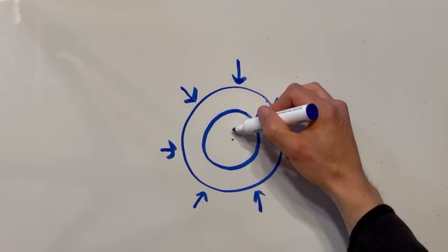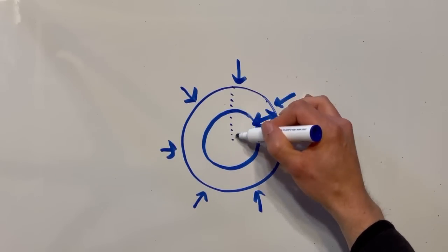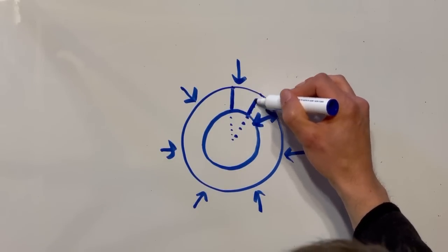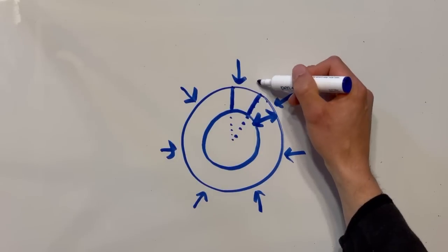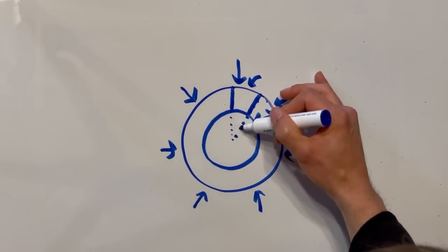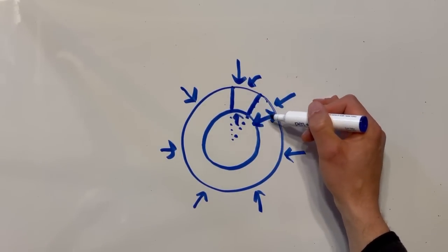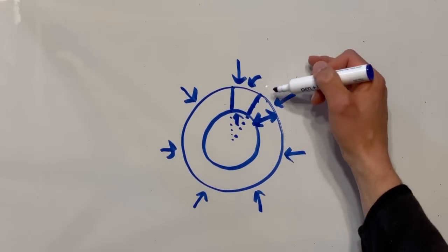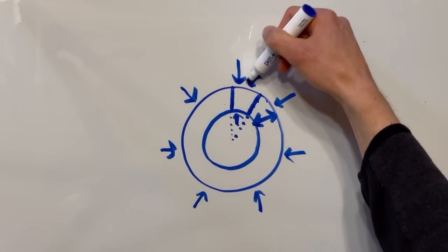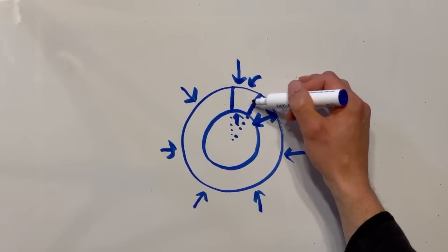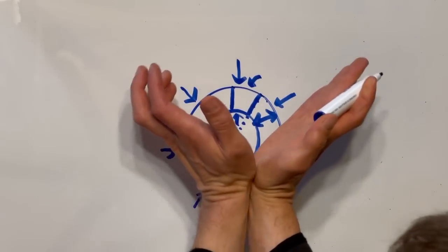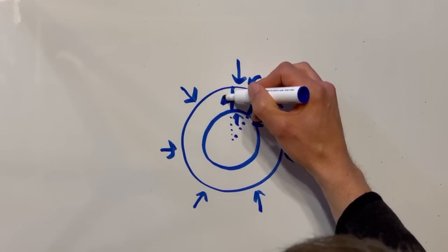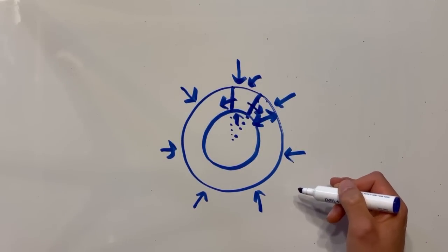Well, if we visualize it and take some dashed lines out from the center, you'll see that this shape looks like a keystone, where it is wider up on the top than it is on the bottom. And what that allows the pressure vessel to do is, say the water is pressing in on this keystone shape, because it's angled like this, it forces out on the neighboring sections of the pressure vessel.